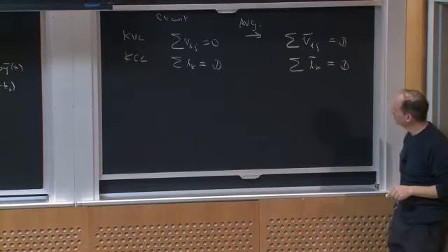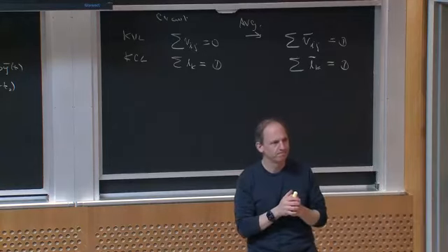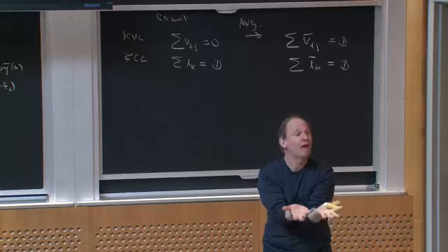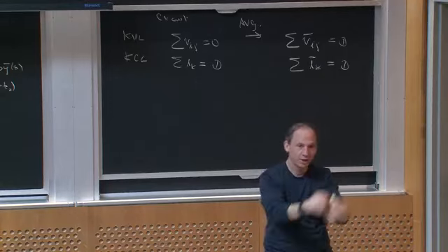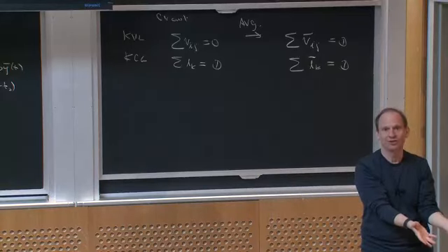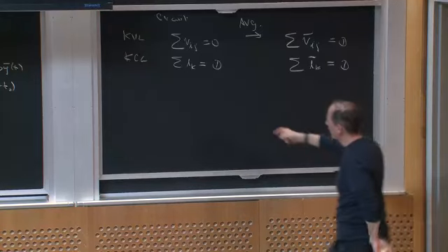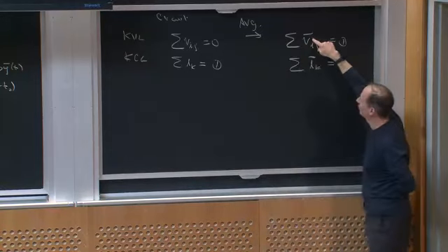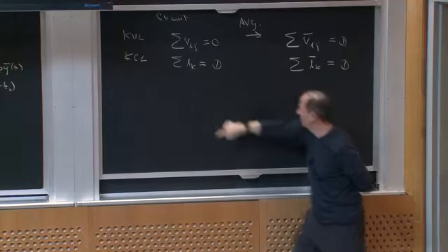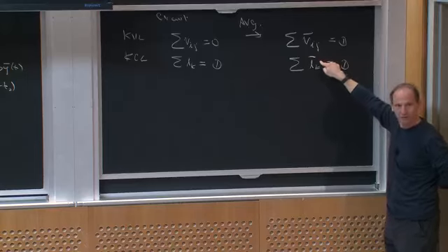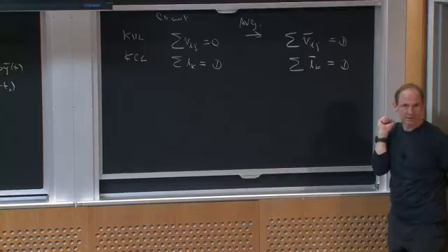Okay? So what I'm really saying here is if I have some circuit, like my boost converter up there, I could apply averaging to that circuit, right, or all the KVL and KCL equations, and I could get another circuit that's averaged that has the same connections in it. Why? Because for every KVL equation in this circuit, there's an identical KVL equation in this circuit, and it just has average voltages. And likewise, every KCL in this circuit generates a new KCL circuit just with average currents. So I can get a new circuit with the same topology for which averages pertain.